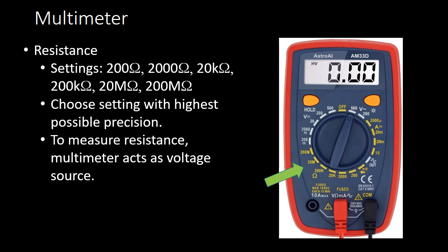And then get the true resistor value. So what you might want to do is take a 220 ohm resistor, maybe one that you've been using to build the blink circuit, for example, and measure the true resistance, and do that as an exercise and find out if it does fall within the range of tolerance. Figure out what the range of tolerance would be, the allowed values according to the manufacturer of what the resistor could be, and then find out if the value falls within that range.